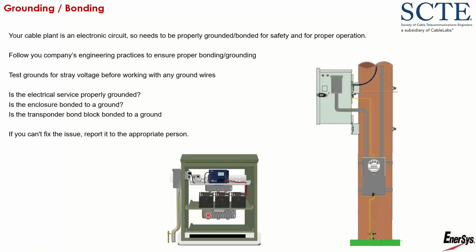And also, don't be grabbing ground wires barehanded until you've checked them for foreign voltage, especially if they're not connected. If you have a ground wire that came loose from a ground rod and you grab the ground wire barehanded and it has straight voltage on it, and then you grab the ground rod, it's not going to be a good day for you.